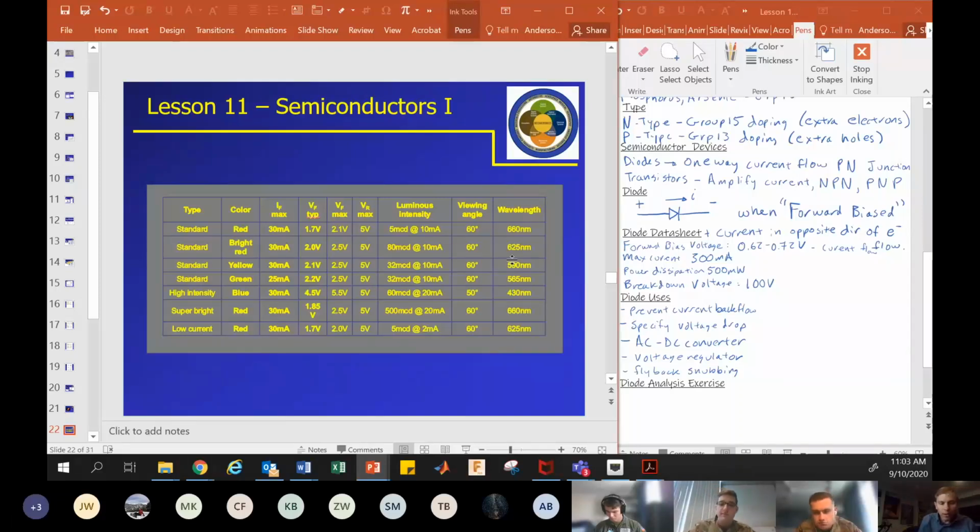Now what I want to show you is, right now I have my Arduino plugged into the 5 volt source, you can't see that. I'm going to plug it into the 3 volt source, and if that were a resistor, we would expect the voltage drop across the diode to change dramatically.